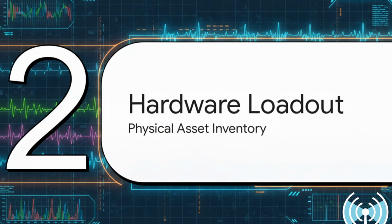Section 2. Hardware and prerequisites loadout. Physical asset inventory. You know what's wild about this loadout? It's surprisingly simple given the incredibly capable architecture we're building. For the physical rig, you need that Zynq-7020 SDR board running embedded Linux, something like Tezuka OS. Grab a standard Android smartphone to act as your end-user device, then you just physically tether the phone directly to the board using a USB-C Gigabit Ethernet adapter and an RJ45 cable. Throw in a high-density power bank, like a LiFePO4, and your physical setup is done.